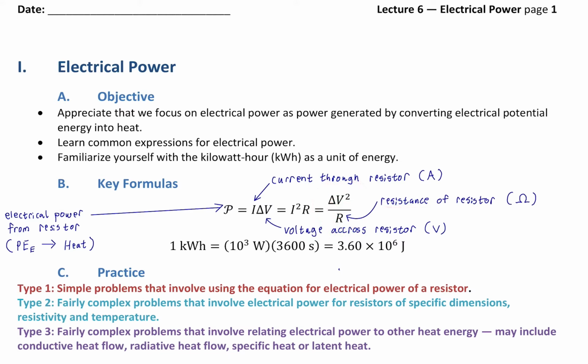So this has some really interesting consequences. If you have a fixed current, then the greater the resistance, the greater the power. On the other hand, if you have a fixed voltage, the greater the resistance, the less the power output. That's quite interesting, right? And it's more common in everyday circuits to have a fixed voltage. Batteries supply a fixed voltage, power outlets supply a fixed voltage. There are exceptions. The most notable exception is a solar panel, which produces a fixed amperage or current as opposed to a fixed voltage.